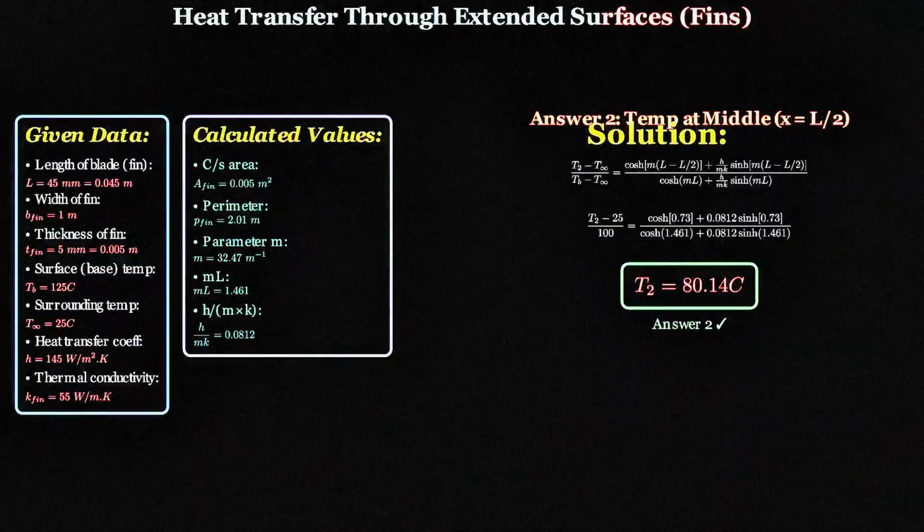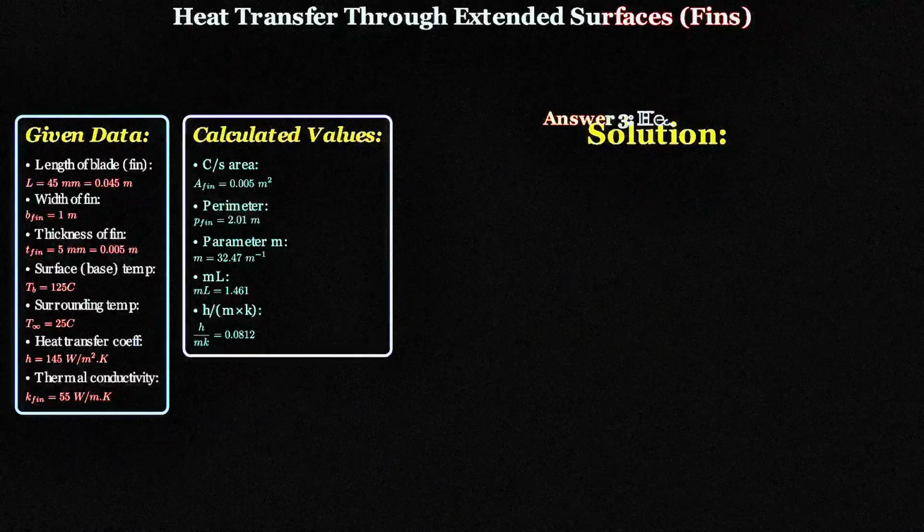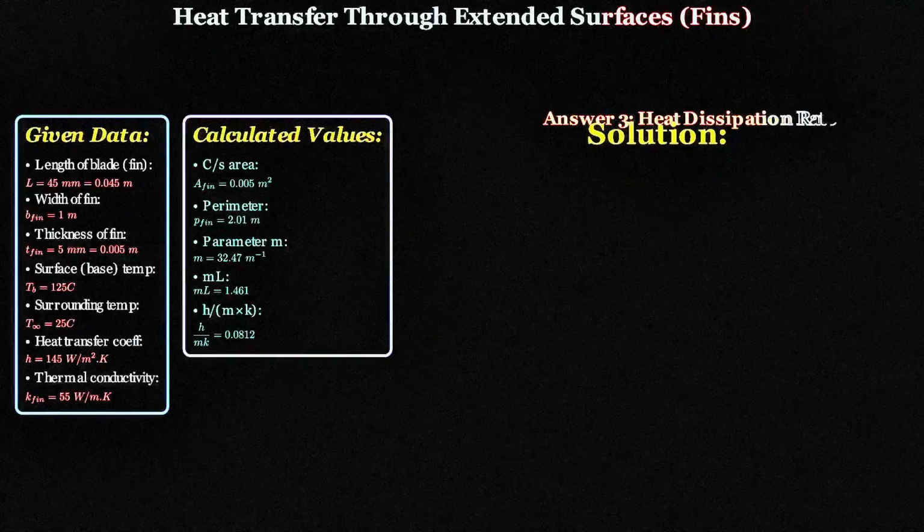Notice that the middle temperature is higher than the end temperature, which makes physical sense, as we move closer to the hot base. Finally, answer 3. The rate of heat dissipation from the fin.